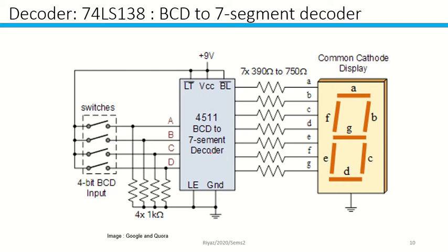Don't forget, your 7 segment decoder must have only 0 1 2 3 4 5 6 7 8 9. Next after 9 is not valid, so you're not going to have that. That's why you're going to have an input of A B C D. So your input A, B, C, D goes inside, is processed over here, and outputs only one.